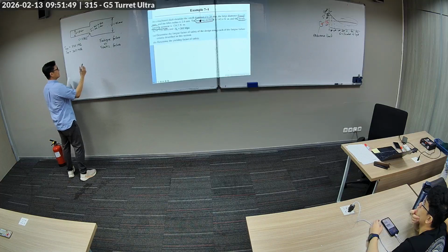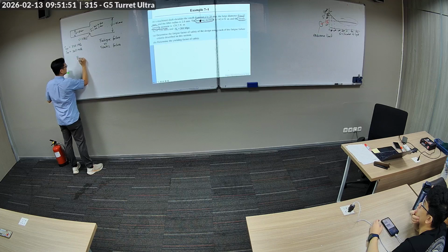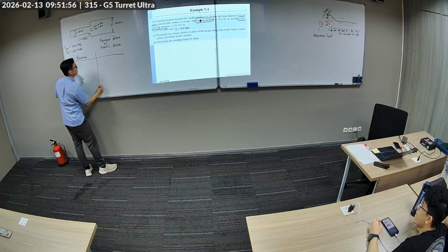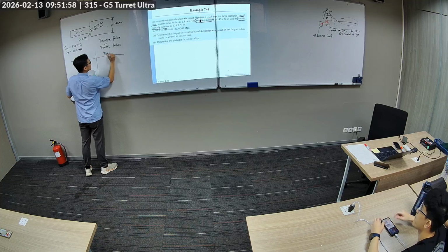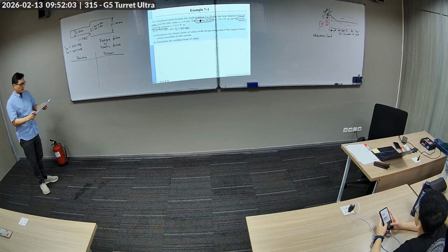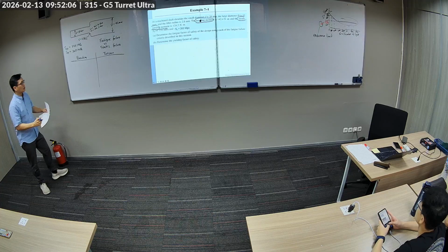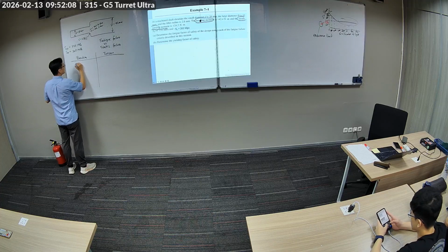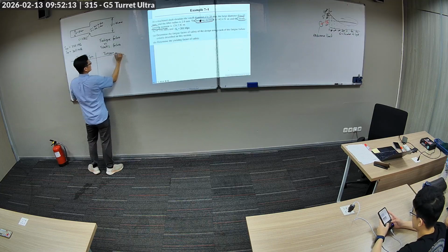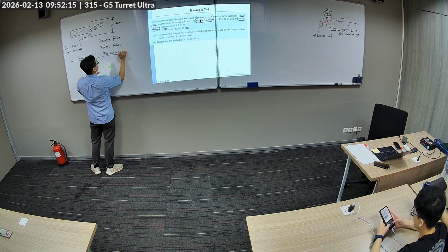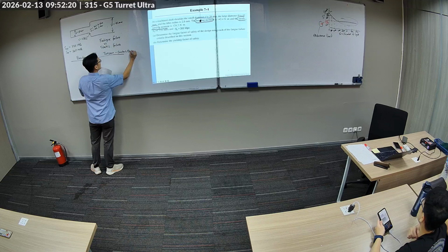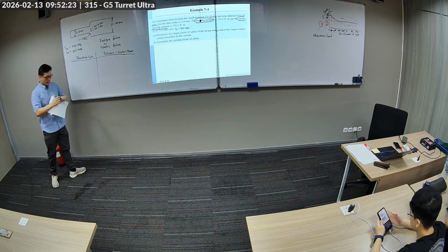So when we want to calculate the stress concentration factor, we have to consider torsion and bending separately. Okay? So there is the bending and there is the torsion. The bending is cyclic. The torsion is constant or steady or static. And this is often the case.